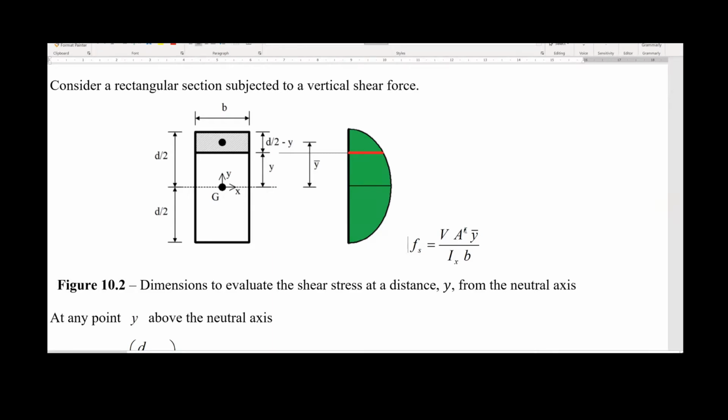The area we are talking about in here is a particular area. If we are going to analyze the shear stress at this red line in here, we need to define the area on top of this line. So what we do is we define this rectangle in here, where b is the width, and the height is whatever it is, because depending on the size of this cross section, this value will be one or another. The area is just the area of this rectangle. So very simple. This area A prime is going to be b times the height in here.